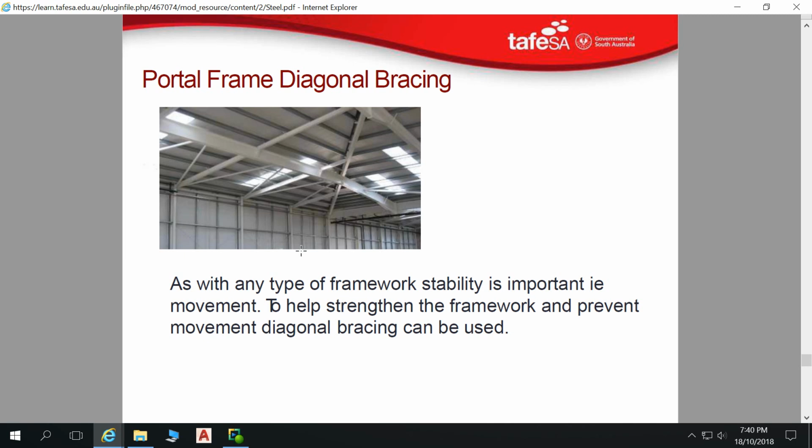What you do is you get a piece of timber, cut the end to a sharp point, hammer it into the ground, then get a spare piece of timber and fire some nails into that piece in the ground, like this, and then tilt your wall frame up till you've got it vertical. You've got your spirit level on it. Get it vertical, fire a nail into there. It's strutted in place, and then your apprentice is free to go chopping up some more timber and making some more frames. So that strutting is used in buildings, but also in the temporary erection of buildings.